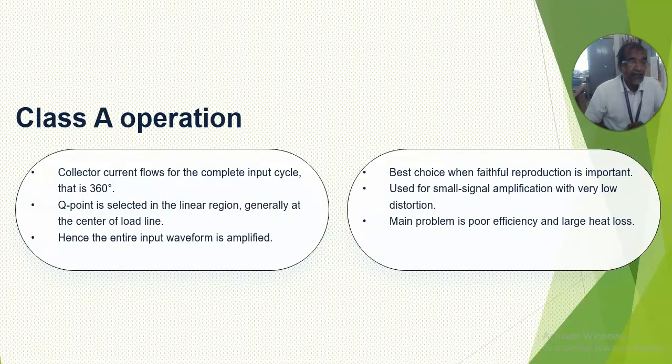Hence the entire input waveform is amplified. It is the best choice when faithful reproduction is important, and it is used for small signal amplification with very low distortion. The main problem is poor efficiency and large heat loss.